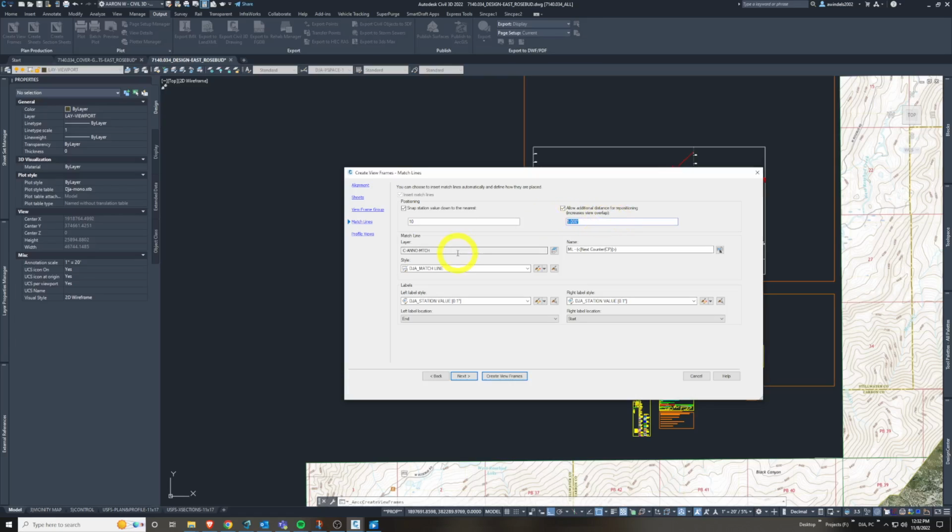It's possible I might not like that. I'll have to go back and redo these view frames. This is some of the stuff that it's worth looking at to tweak now. It's easier. So here we could rename the match lines. I'm just going to let them count up from 1. There are other variables. Instead of doing the next counter, you can insert here.